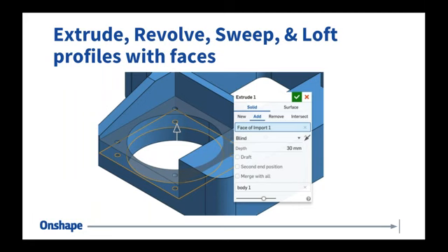When doing an extrude on a face, does a solid or another face? Well, it's important to keep in mind if you're importing with surfaces, right? There are many solid steps that you can import, but if you're importing with just surfaces, then you have the same rules that would apply with surface modeling geometry. So if that's what you mean by typically faces only, if you're importing just surfaces, not solid geometry, then you have the same rules.